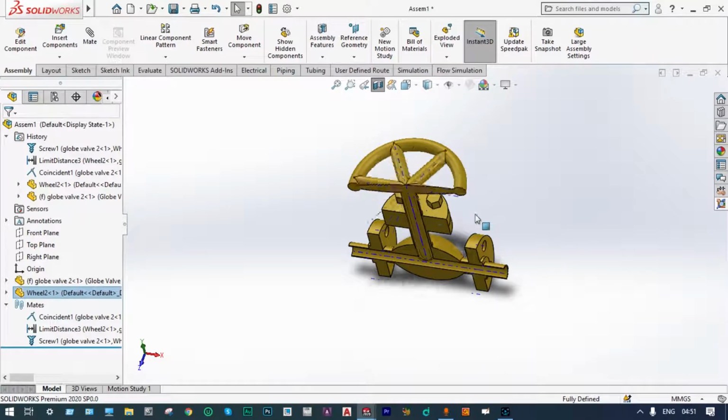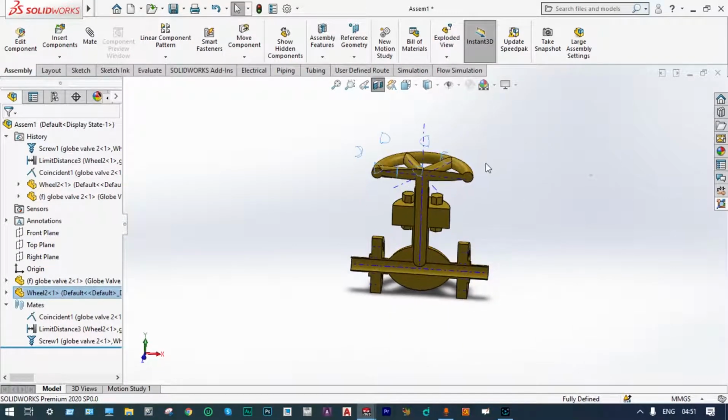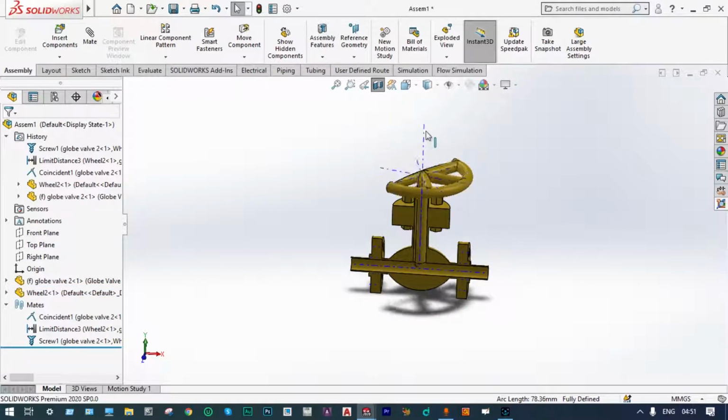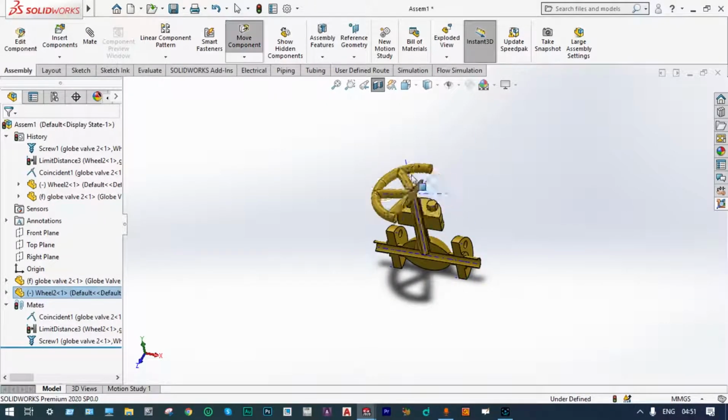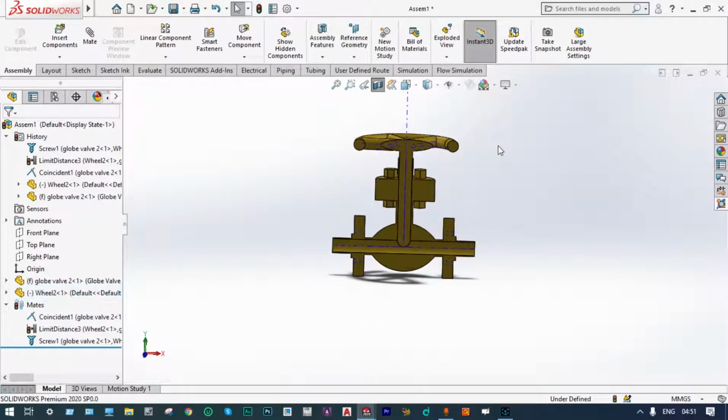We can do this one manually, we can do automatically also, right? At this location, let us move down more. With clockwise rotation of this wheel, the plunger will come down more. This is the position. Now at this specific location, we can start one simulation, and in the parametric study, we will have a different rotation of this wheel, and with the different rotation of the wheel, we will see the different goals like pressure, temperature, velocity at the exit location. So we can start this one.